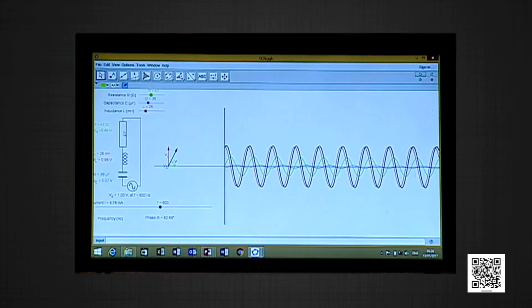Here we have L, C and R in series, and we can see how, when these three are connected in series, the voltage and current across the resistance, inductance and capacitance vary. This phasor diagram is showing it like this. Again we have 3 buttons. If we change the value of R, we can see how the current and voltage behave. Both are directly proportional. This green graph is showing that.